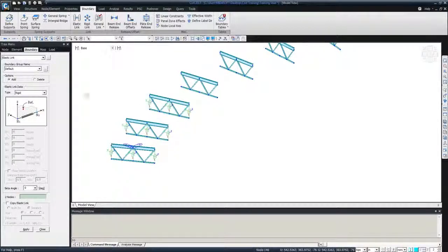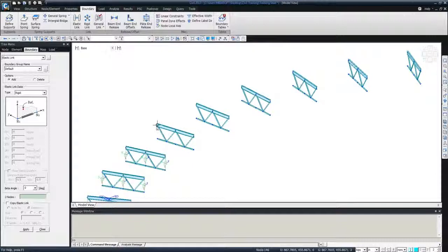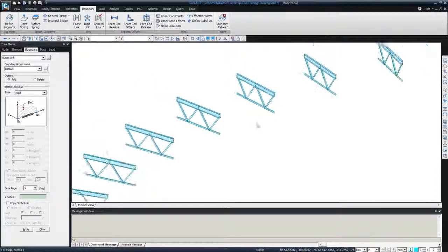And if you're doing construction stages, which we are not modeling today, ensure that you select the correct boundary condition, because construction stages are all about the groups. At that point, we're going to have the structural groups, boundary groups, and load groups, and then we activate and deactivate them at different stages of construction.